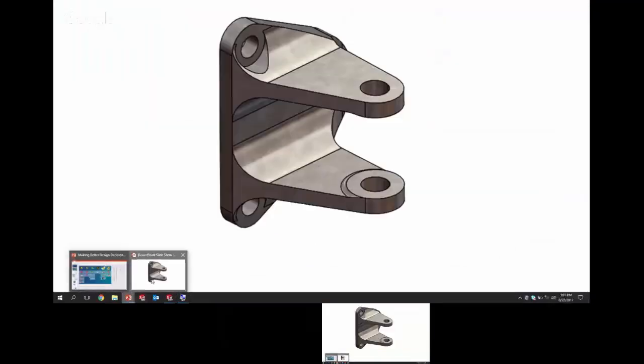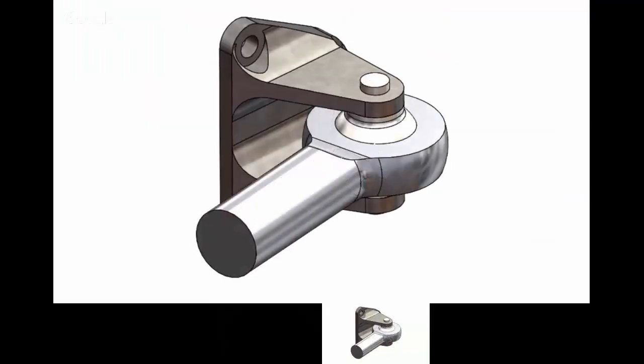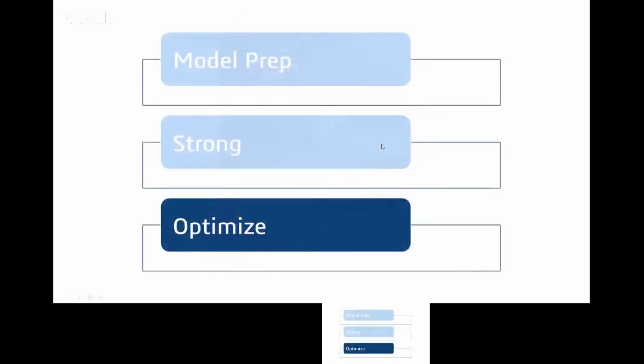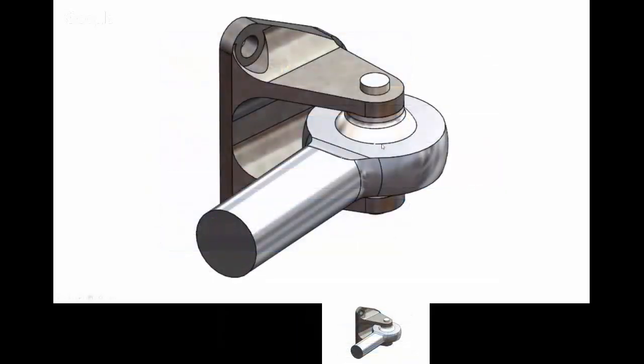Right? So starting small in terms of simulation, then add on a little more geometry. You don't have to throw a ton of geometry at it. But here I can get the pin behavior to add a little more detail. Now, in the real model, I also had a threaded rod coming into this spherical ball end. I may not need that.